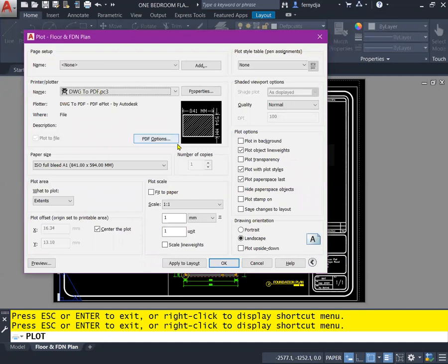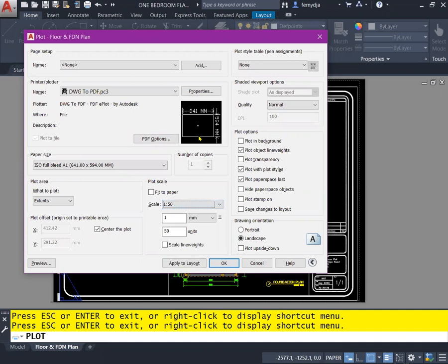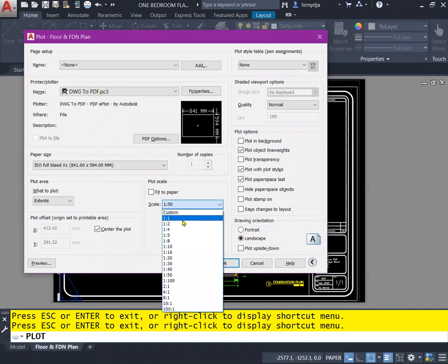Now, if I come over here, down here it says plot scale. You notice the default is 1:1. And that is why the print preview displays the drawing exactly how it is on the sheet. Now, if you decide to scale it 1 in 50, what you're literally doing is scaling the drawing again. If you check your print preview, everything is too small because you've scaled the drawing, and then on top of that, you come back and scale the sheet. So everything is too small. So by right, I just press escape to get back to here. This should be saying 1:1.